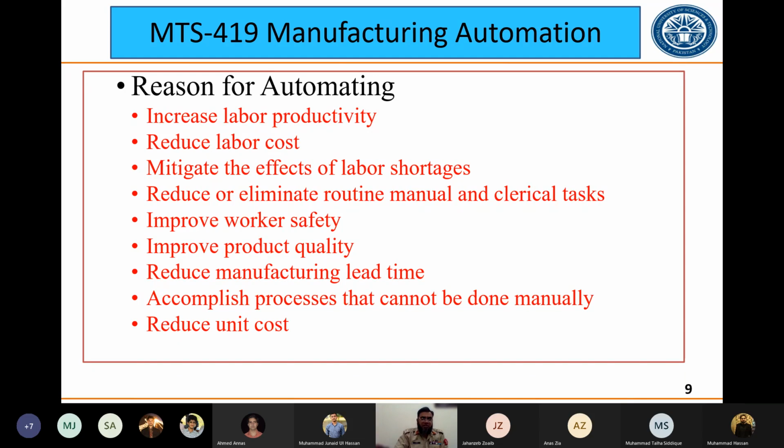So manufacturing lead time is something which is defined as, we will talk about it in detail also. We will carry out some calculation, and formula, we'll see its formula also. So manufacturing lead time is the time which a part spends in the factory. So a raw material comes in and the finished product goes out.